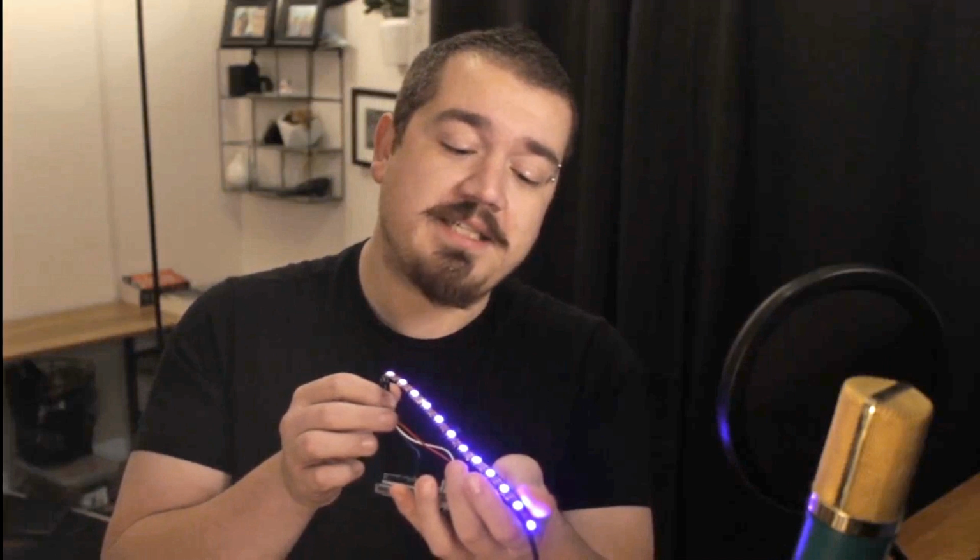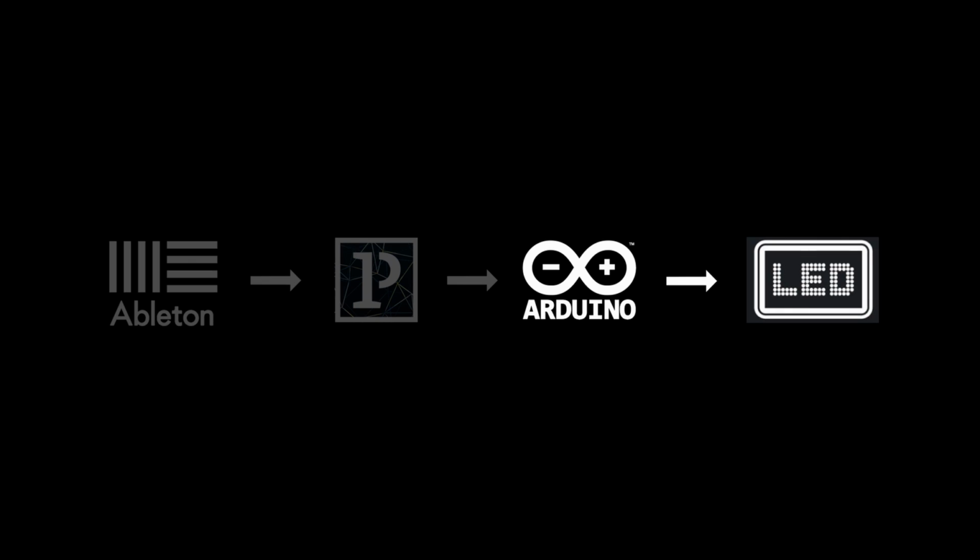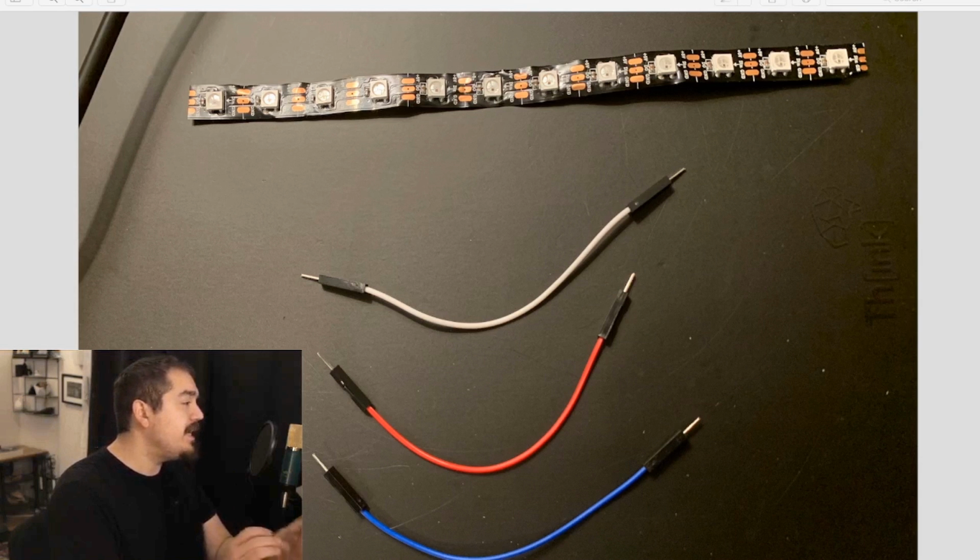We're going to build this little LED strip that is going to let us control some pixel art directly from the Arduino. To make this, you're going to need a short strip of Neopixels. The board can't actually power that many. I've got 12 here. It's a pretty reasonable number. And then just a couple of short jumper wires. Here I've got white for ground, red for power, and blue for data, but you can use whatever you got.